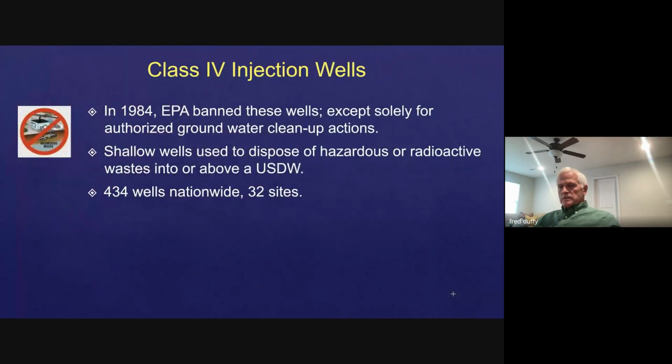And let me see what else. Okay, class 4. These are the wells that in 1984 were banned by EPA, but now they're only authorized for groundwater cleanup actions. These wells are shallow. They usually inject into the USDW. 434 wells nationwide at 32 sites.